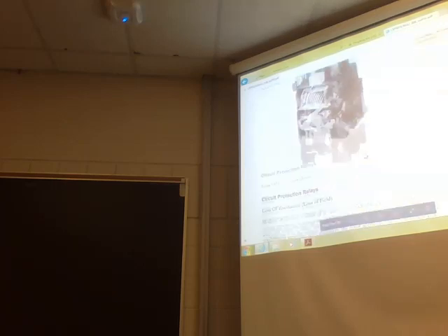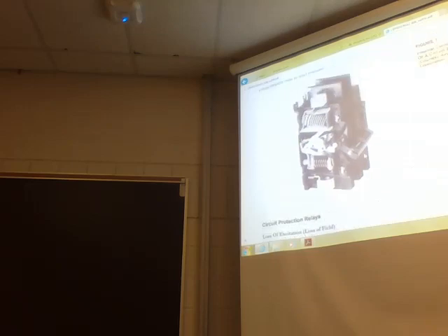Anytime a breaker trips, find out why. Don't just turn the breaker back on again. If there's been a short circuit in a fuse, it destroys the fuse, and you have to replace it. If it's a short circuit in a breaker, it's possibly done some damage, and if you keep resetting it and trying to make it without checking the problem, you are definitely damaging the breaker.